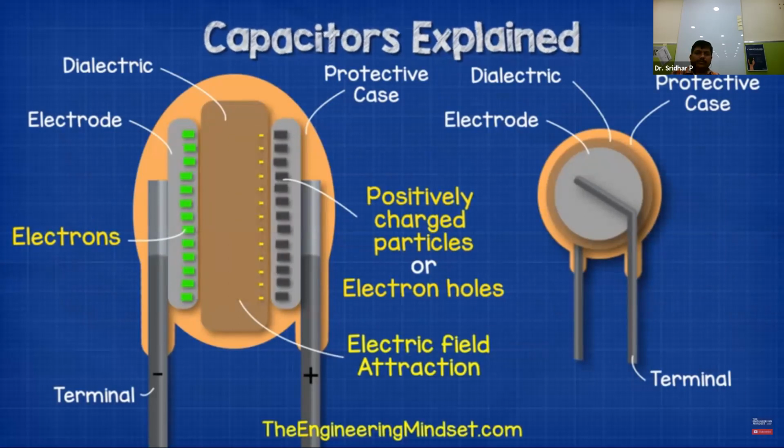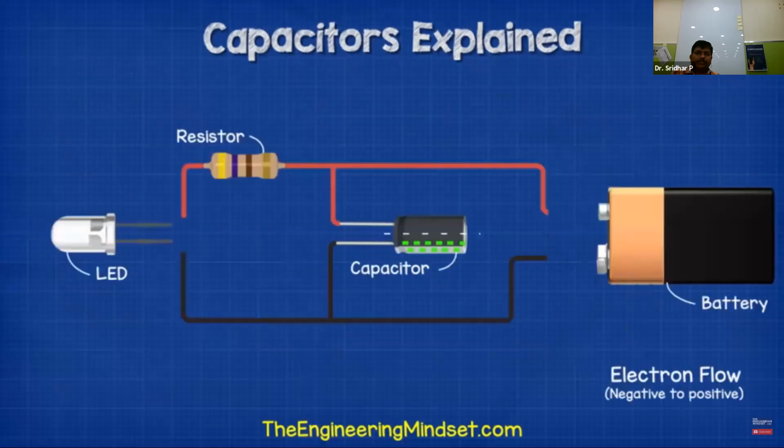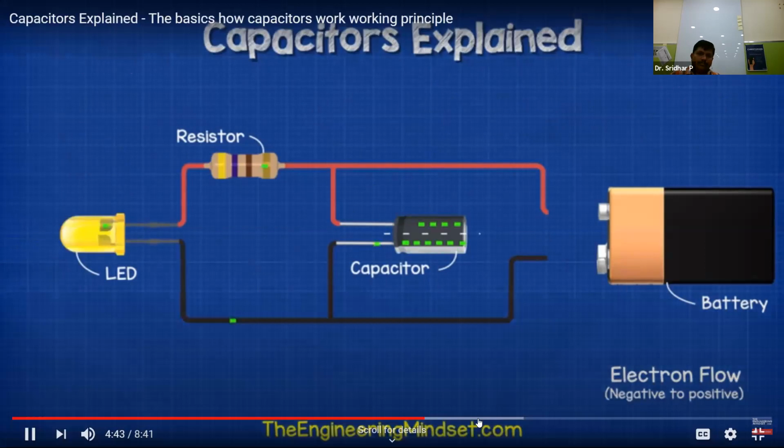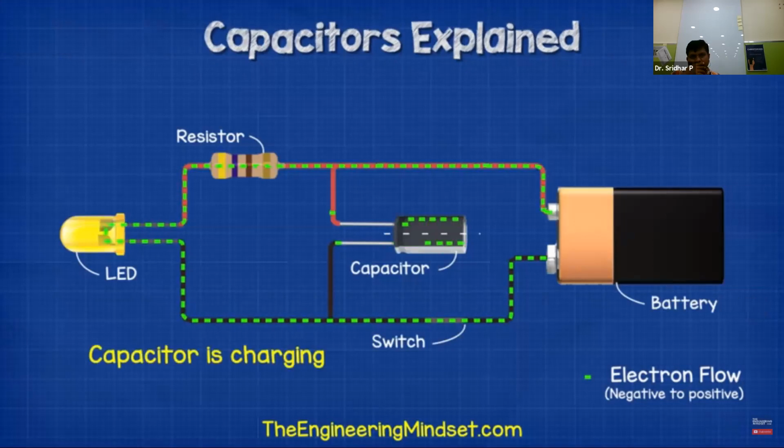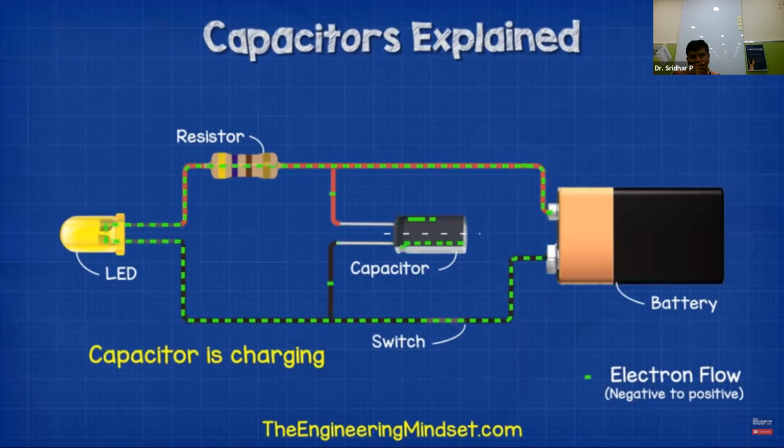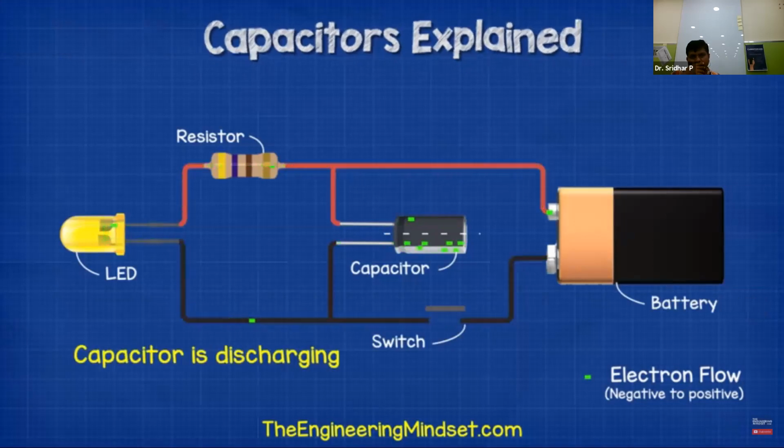If we then place a small lamp into the circuit, a path now exists for the electrons to flow and reach the opposite side. So the electrons will flow through the lamp, powering it, and the electrons will reach the other side of the capacitor. This will only last a short duration though until the buildup of electrons equalizes on each side. Then the voltage is zero. There is no pushing force and no electrons will flow. Once we connect the battery again, the capacitor will begin to charge. This allows us to interrupt the power supply and the capacitor will provide power during these interruptions.